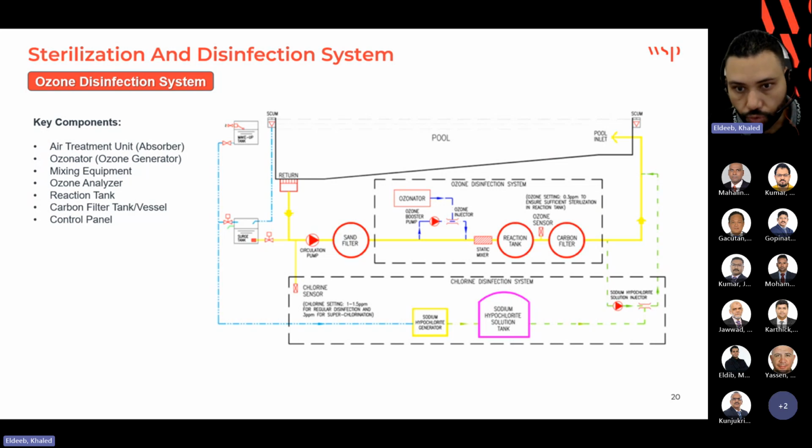We monitor ozone concentration in water to maintain optimal levels and to ensure compliance with the health and safety standards. And number 5, we have the reaction tank. This tank provides sufficient contact time. We allow around five minutes for ozone to react with the contaminants, and this allows oxidization of bacteria, virus, and